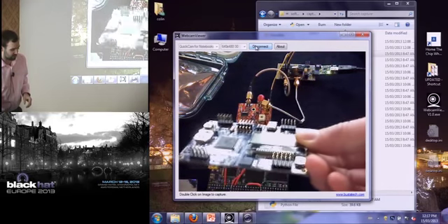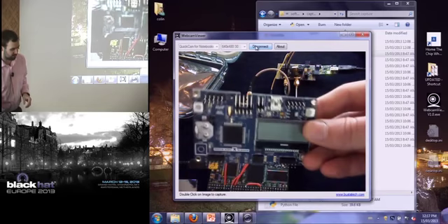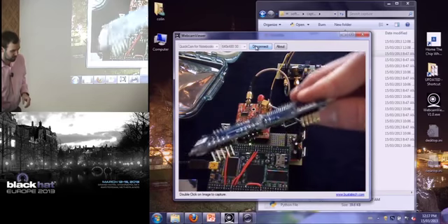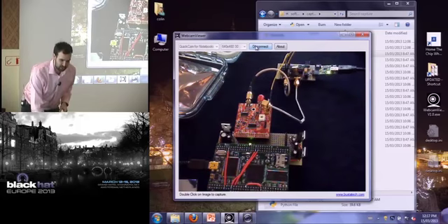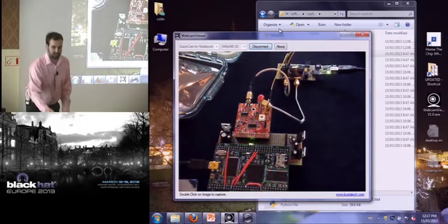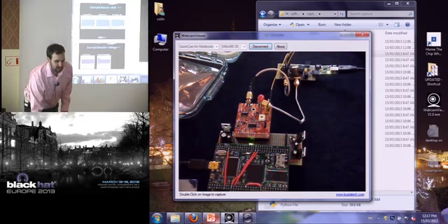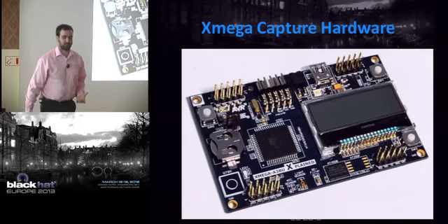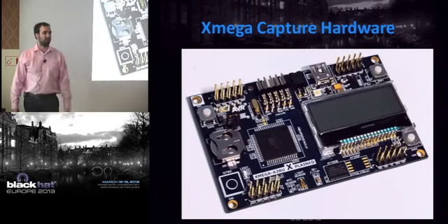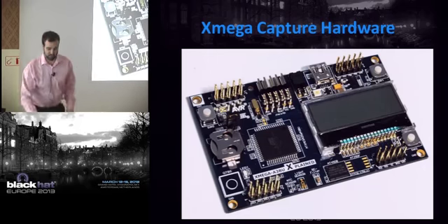This has a 2 megasample per second ADC built into it, as well as USB. So if you use this and can get it to synchronize properly with your target, you may be able to actually do an attack, not on a real device, I wouldn't say, but you can do an attack for learning purposes to test some of your own algorithms for $30 hardware, complete with everything.